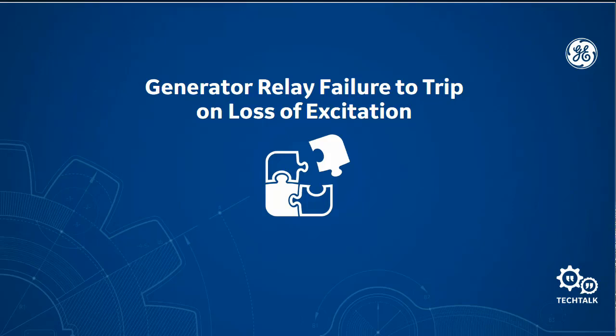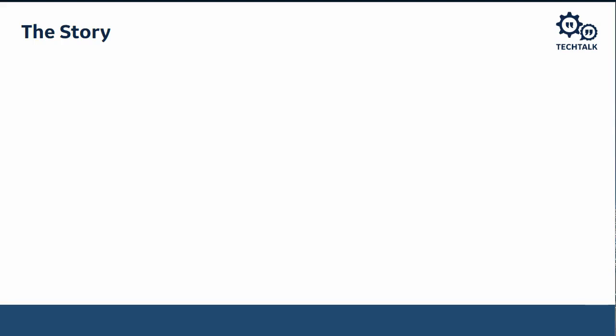So this first event is a generator relay failure to trip on loss of excitation. So here's the story. They lost the exciter. Now at this point, the appropriate question is not to ask where they last saw the exciter, because that's not what they meant. They meant they tripped the exciter offline. So the exciter's been tripped offline, and they have a loss of excitation element, and they expected it to trip, but the loss of excitation element didn't trip. And so let's look at those questions.